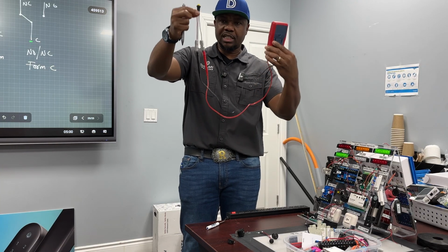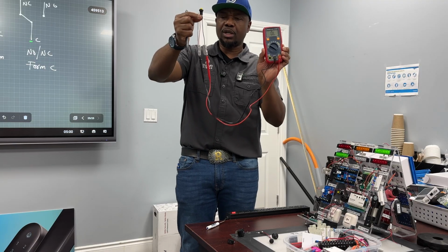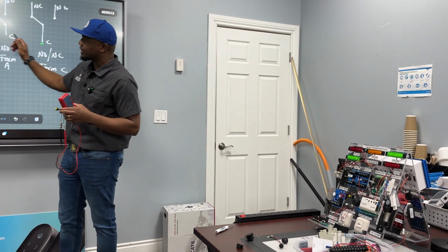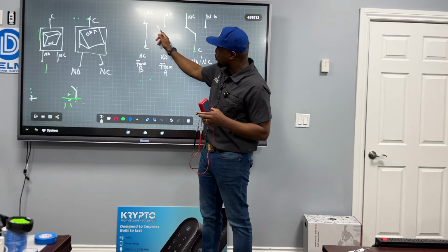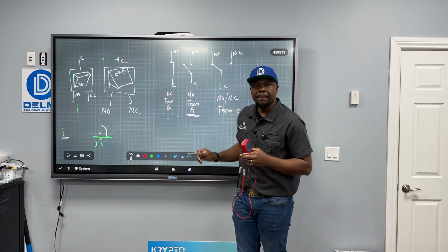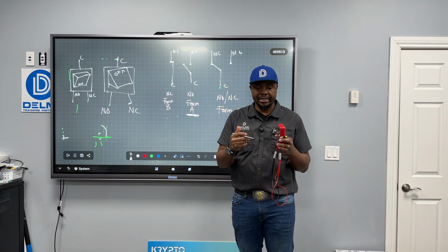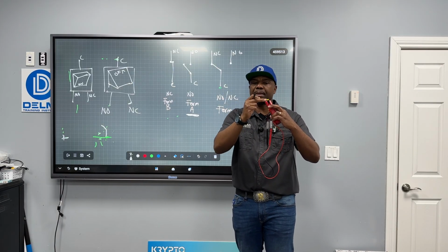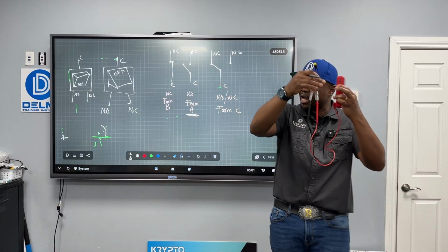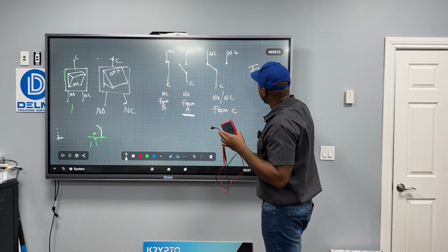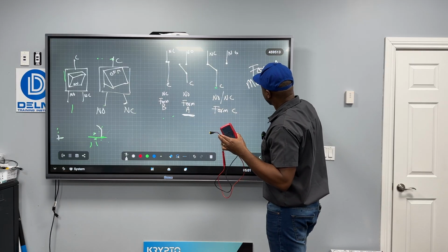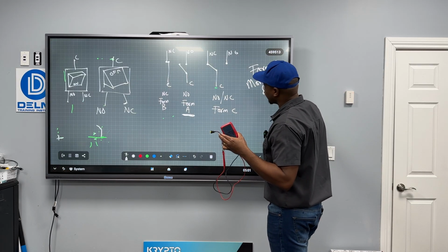So first of all, just by looking at this in the default state, even though it's connected and there is no beep, when I look at these two switches, which one is it? It's this one because it's open, right? So this is a Form A switch. But is it a momentary or a maintained? It's momentary because when I take my finger off, the sound goes away. So this one here that we're working with is a Form A momentary switch.